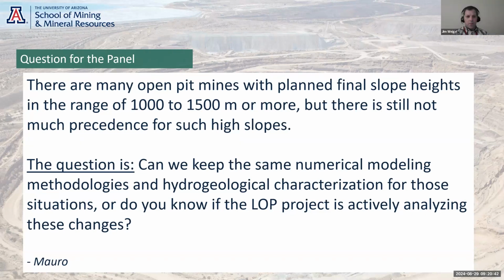Yeah, I just want to also put in one more thing too, is you need to have some breaks in the slopes where you can put in piezometers mid-slope. So if you don't, you become completely blind, or you put them in only to lose access to them, and then they go down because they're hit by a rock or any number of things.